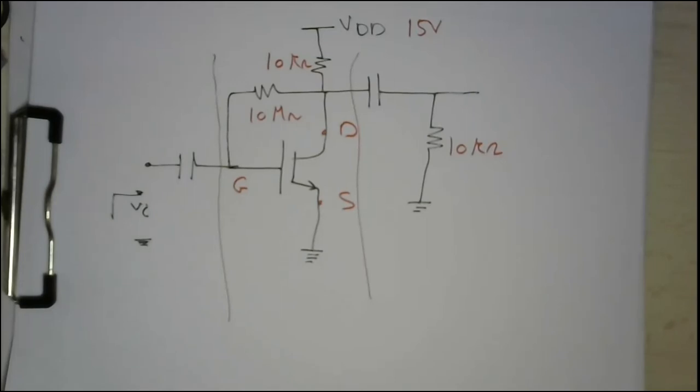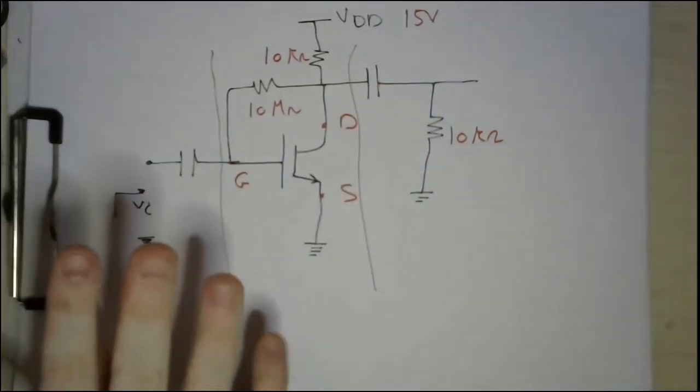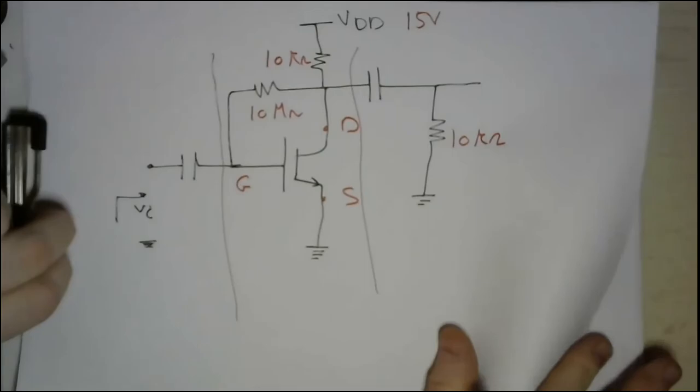So, as we did in the first part, the first requirement in this stage is just to replot the circuit in the AC format. So we'll consider these two capacitors as a short circuit and plot the same circuit again. Here.